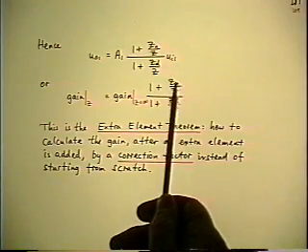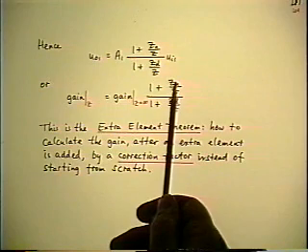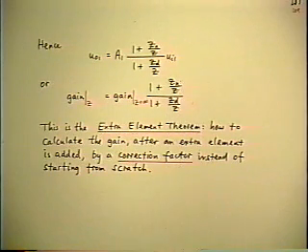And you see, the only catch to it isn't really a catch. The only thing that causes a little difficulty is that one of the driving point impedances, namely Zn, is calculated under this null double injection condition, in which you have 2 inputs simultaneously and you adjust them in order to null a different quantity.